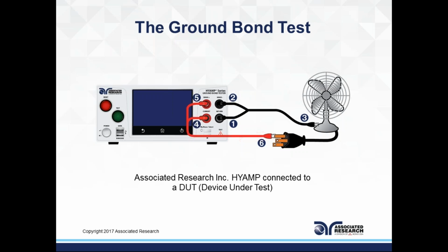So what do we define as a system? Any kind of internal resistance to the tester, any kind of resistance that comes from the test leads. So you want to be able to offset this and not count it towards your product, because your product doesn't really start till the ground pin of your adapter and ends at the metal chassis of your product. So if you had maybe 5 feet of cable or 10 feet of cable before you got to your product, every foot of cable would add some kind of resistance.